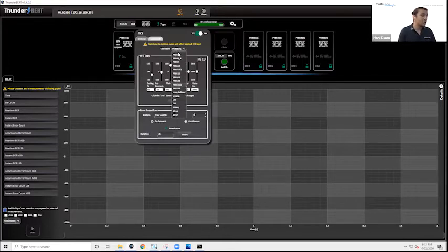I can go ahead and change the PRBS signal. Right now, I have PRBS 13Q being transmitted on all the receivers, but I changed that to PRBS 7 on the transmitter, and you'll see my PRBS 31Q receiver has lost lock. I'll switch that back to PRBS 31, and I'm right back where I was before.